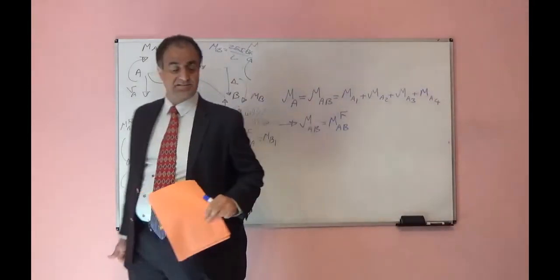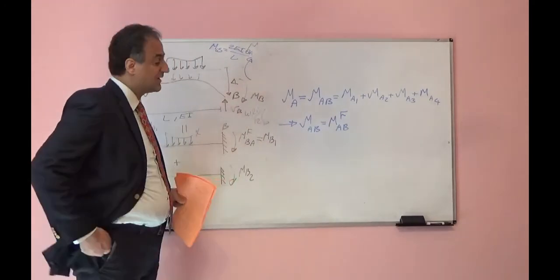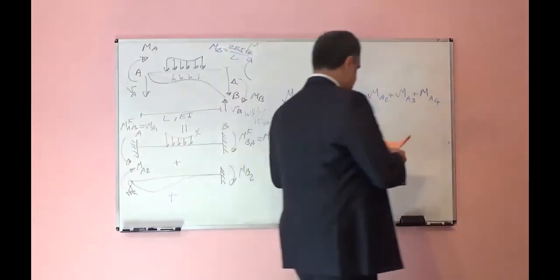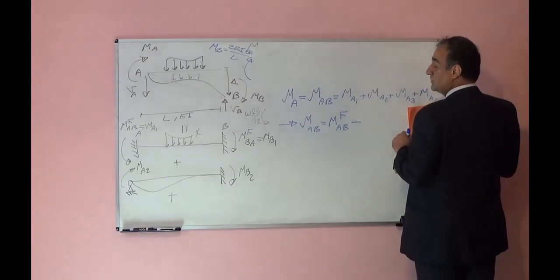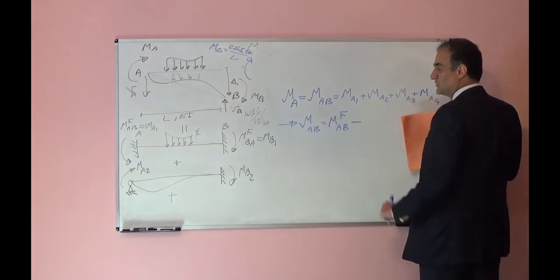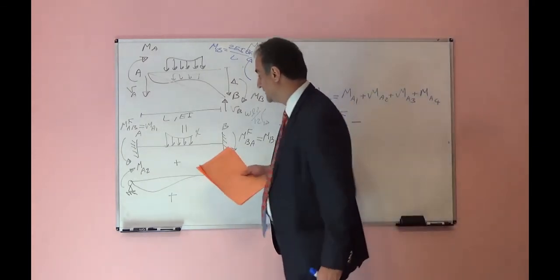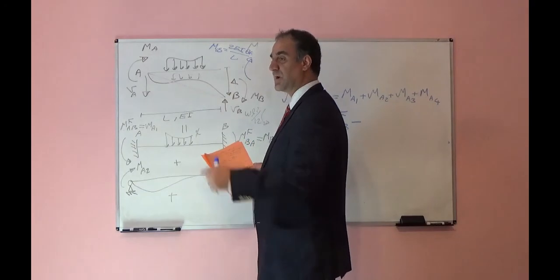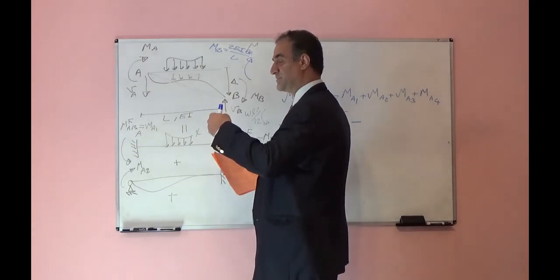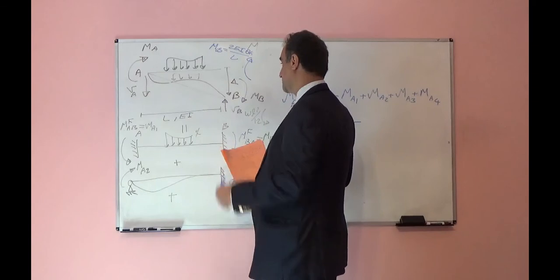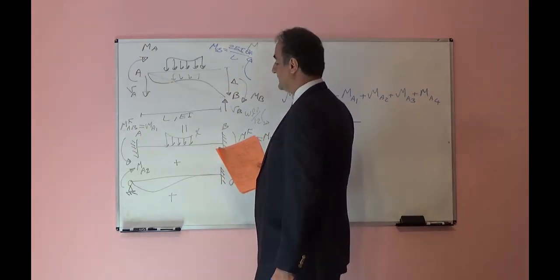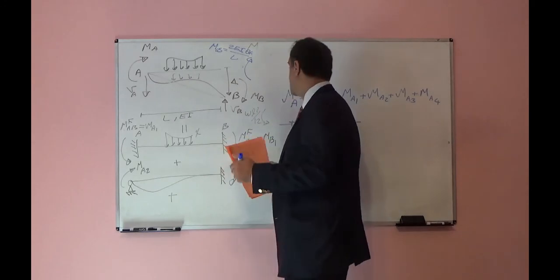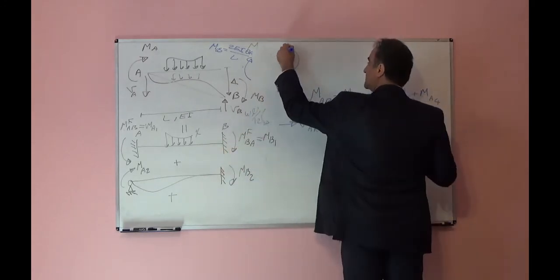support reaction because of external load, as I explained, we can find from the table, plus or minus depending on your direction. You assume it is positive or negative. If I assume counterclockwise moment is positive and counterclockwise rotation is positive, clockwise will be negative.